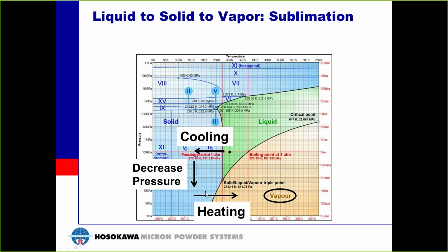This is important because you want sublimation. What would happen otherwise is you would have melting and then vaporization or evaporation, which is not what you want to occur. You want the product to go strictly from a solid to a vapor.